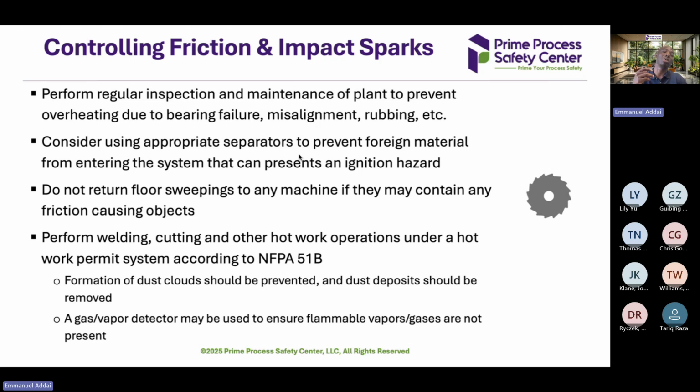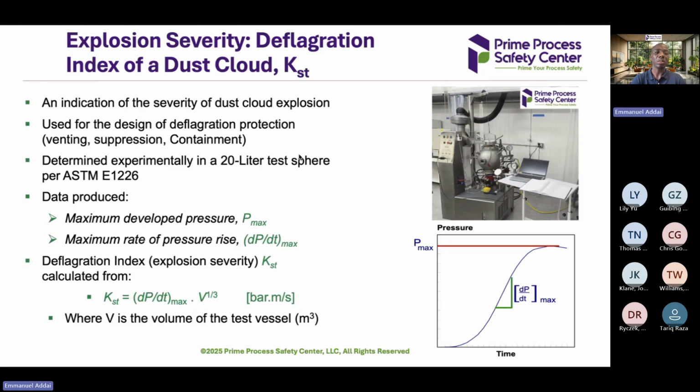And also, anytime you are doing hot work such as welding, cutting, you need to have a permit to ensure that all the various explosible materials are removed from the system before doing hot work. And I think there was also an incident, I think this year, where they have an open system. They were doing cutting and some of the embers from the process flew into the system and actually caused a fire hazard, and it cost the company a lot. So always before we do anything, we need to take good precaution before we take any action.